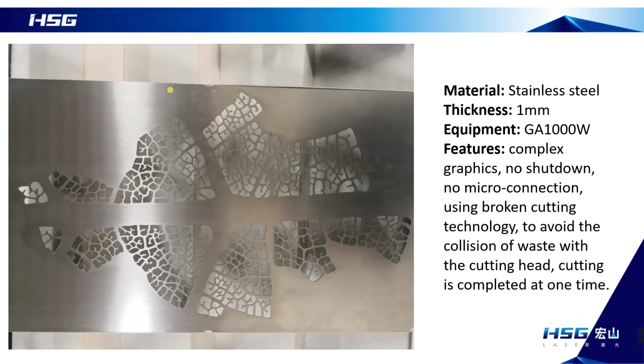This one shows the broken cutting technology. Also, 1mm of stainless steel uses a 1000 watts laser to cut a complex pattern. Normally, if we are going to cut a complex pattern, we might attach it to keep it from falling, and then we take it down manually.